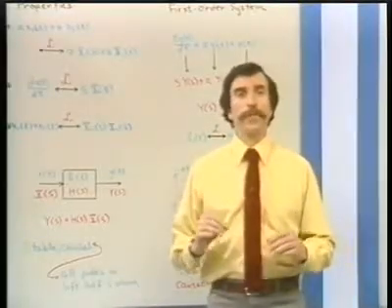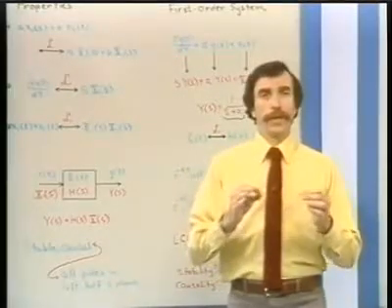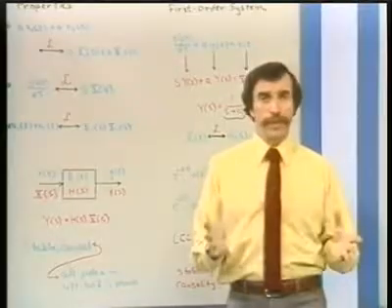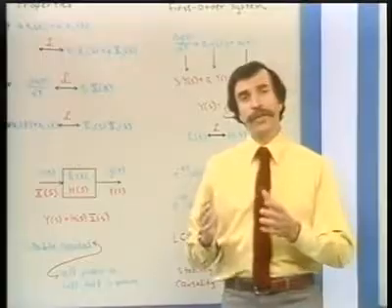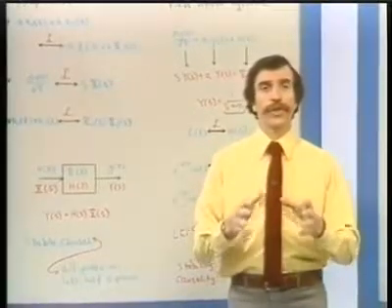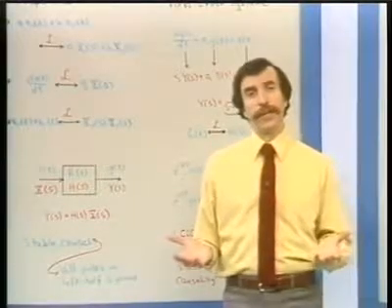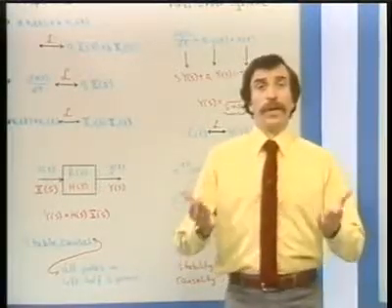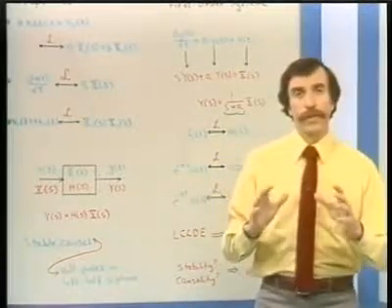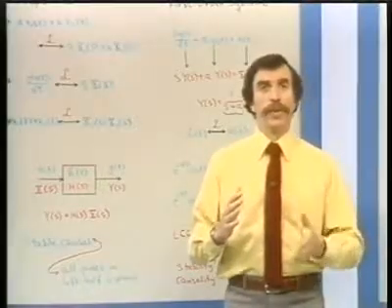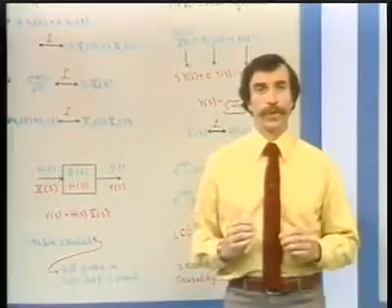For example, we know from previous discussions that there's a condition for stability of a system, which is absolute integrability of the impulse response. And that, in fact, is the same condition for convergence of the Fourier transform of the impulse response. What that says, really, is that if a system is stable, then the region of convergence of the system function must include the j omega axis, which, of course, is where the Laplace transform reduces to the Fourier transform.